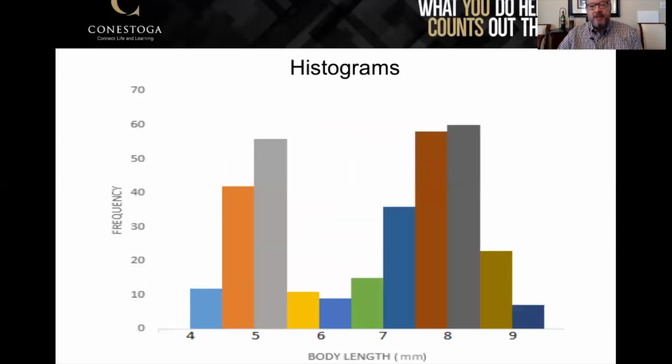Next one, histogram. So histograms are, as you can see, they look like a bar chart, but they're designed to look at the distribution of data. And histograms let you see distribution data that doesn't follow a traditional simple bell curve, right? So you're probably familiar with the bell curve kind of structure where you have your average in the center, right? And then how tight or how flat has a lot to do with the tolerances of a process.